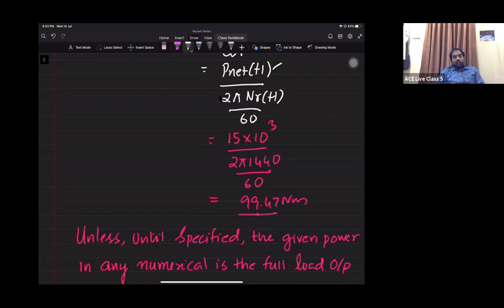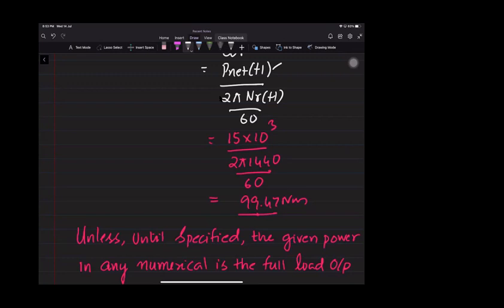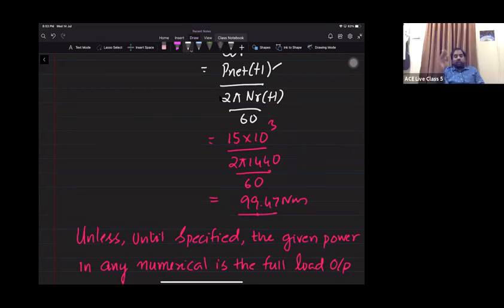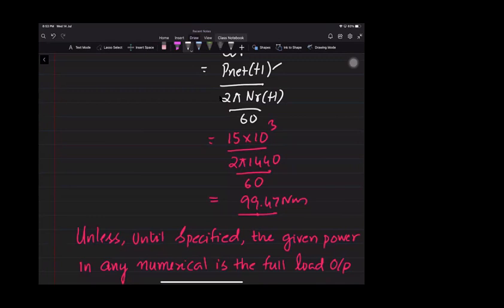When you are decreasing the voltage by 10%, then obviously from 100 Newton meter, the torque will be reduced to 80 Newton meters. Yes. But when I'm talking about full load torque, the full load torque will be something like say 200 Newton meter. Then when you're decreasing the voltage by 10%, then the torque reduces to 160 Newton meters. Yes. That means that slip is constant there.